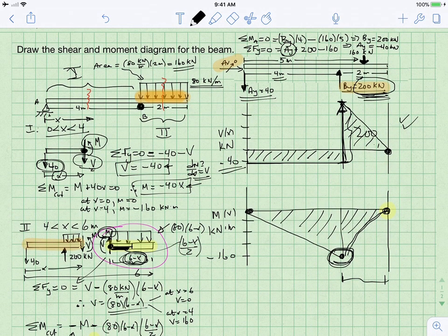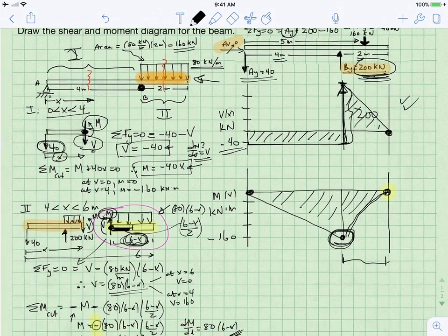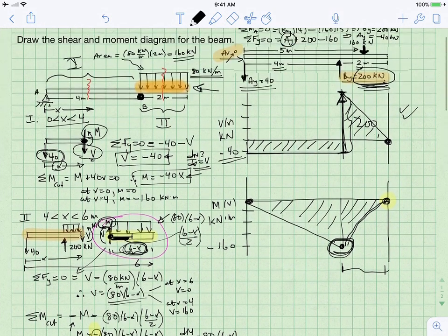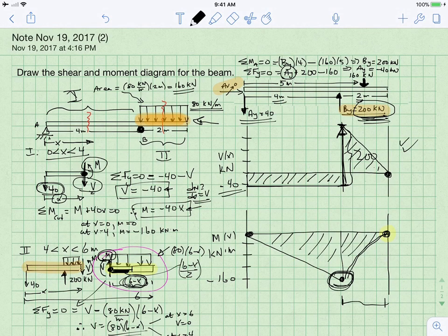In closing, we did two new things. We started thinking about distributed loads and how they work. The second thing is that we no longer had a beam supported only at both ends, but a beam that's hanging off the end. You can see what that does: it creates a pretty intense shear on that beam as it hangs off the end. Of course, as the beam provides no load at the end, there's no internal shear at the end. But immediately following that B, the shear is pretty high. All right, that's it.